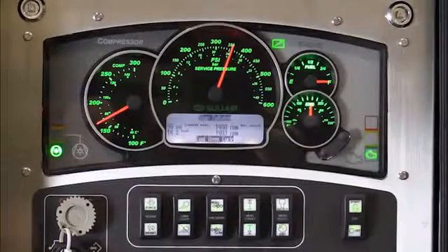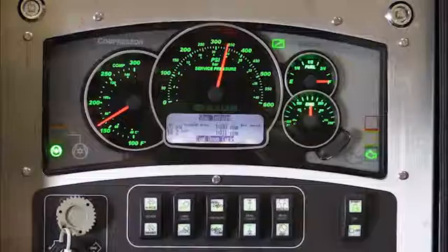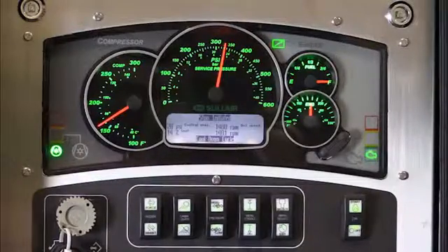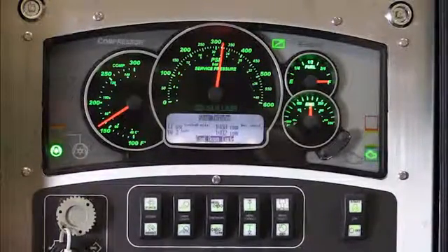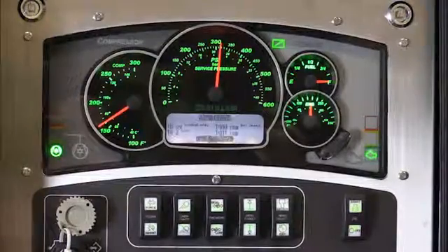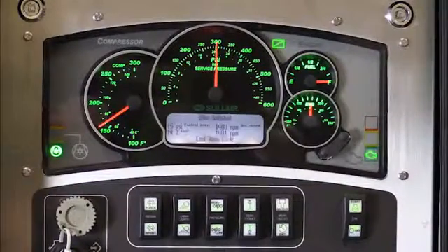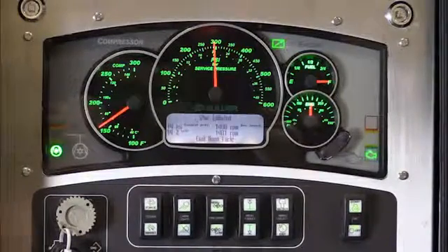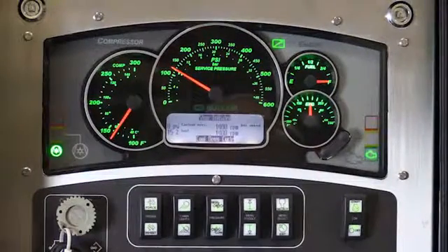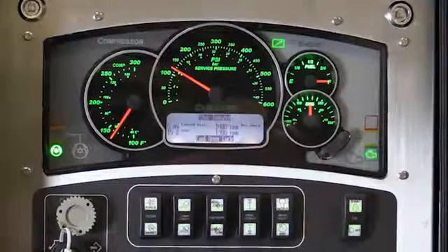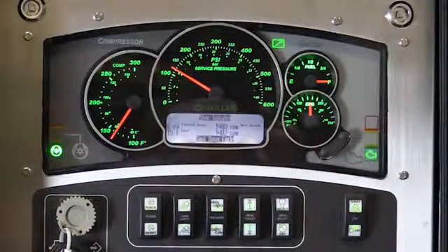During cool down mode, the desired RPM of 1400 or minimum idle speed is demanded from the engine. The inlet is held in a fully closed position in a forced unloaded state. It will remain in cool down mode for approximately 2 minutes. The purpose of cool down mode is to cool the turbocharger.